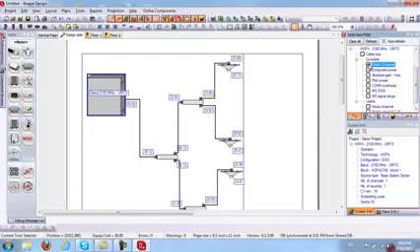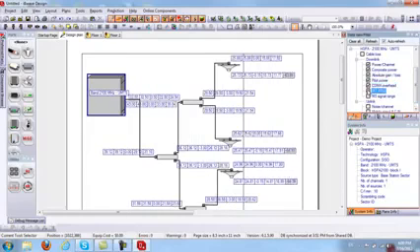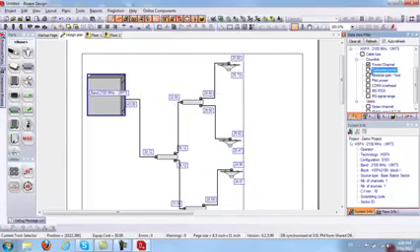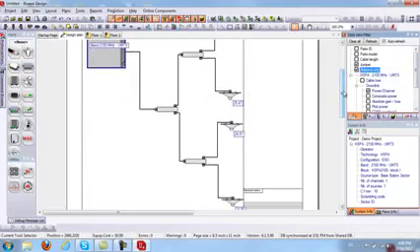So I can display my power per channel, my composite power, absolute gain and loss, pilot power, CDMA overhead, MS RSSI, MS signal range. So I can display all my calculations or hide them if I want to. So I can just uncheck the boxes and easily hide my calculations. For power per channel, I can have it displayed at the antenna level only. I can check this box here, and automatically I have the output power at the antennas only.